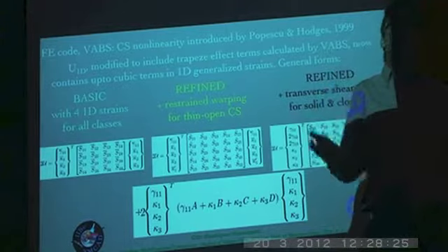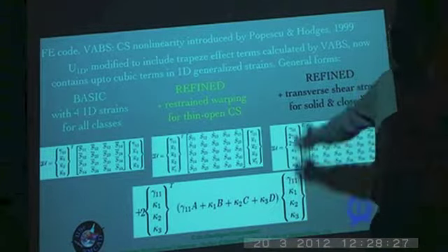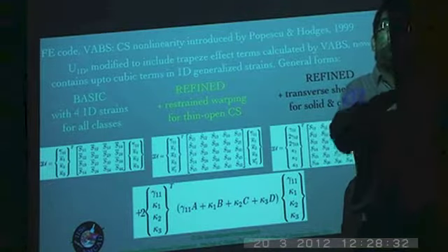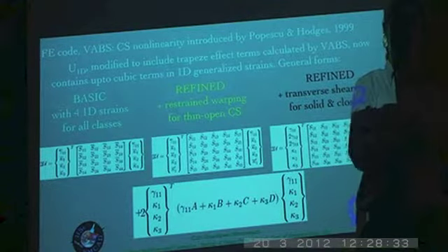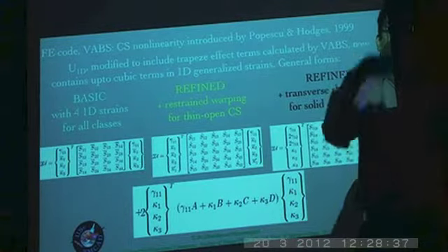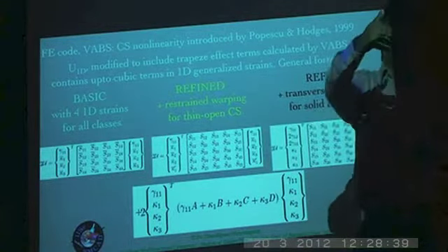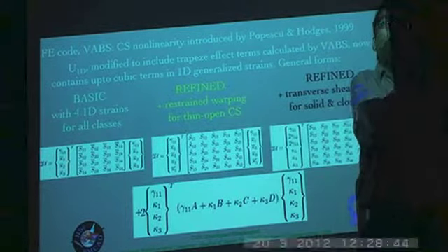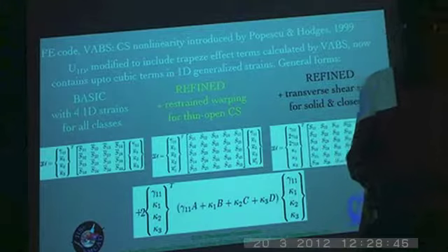In some cases, they might make a difference only up to 1%. And in cases that you are referring to, for example, you have a solid cross section and you're talking about the Brazier effect, the effect might be as small as 0.1%. So you just don't care about it. In an asymptotic sense, they would appear in third or higher order approximations, not up to the first or second order approximations.